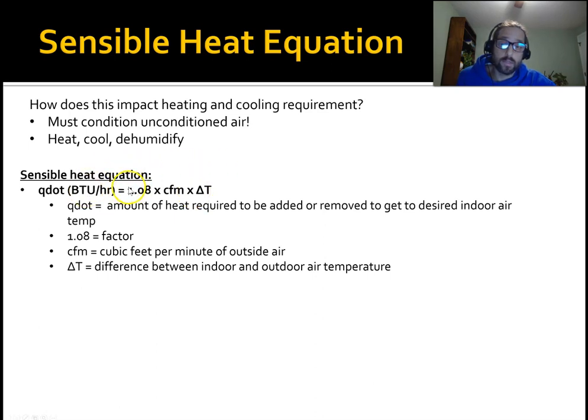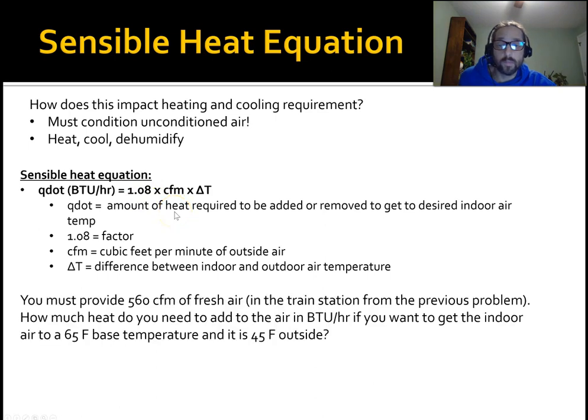You use this sensible heat equation. So that's cubic feet per minute of outside air, times the difference between the indoor and the outdoor air, times 1.08. So it's actually, again, a pretty straightforward equation. Let's just do an example here.